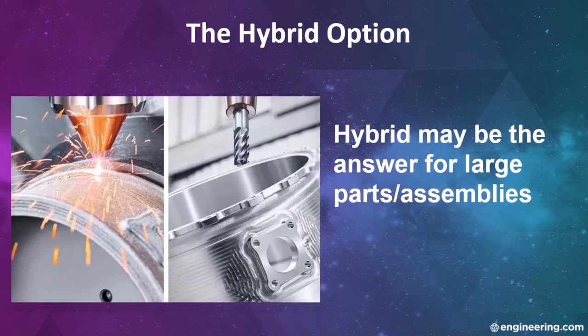And this opens up some interesting design possibilities for tough, hard-wearing surfaces deposited on softer, more ductile substrates, or the exact opposite, with lower cost, friable surfaces that can be remanufactured in the same equipment that made the parts in the first place. The obvious applications for larger assemblies include things like bosses, lugs, brackets, flanges, and as hard-facing processes for assemblies in extreme environments. Valve components for the energy and process industries use this technology to good advantage now.